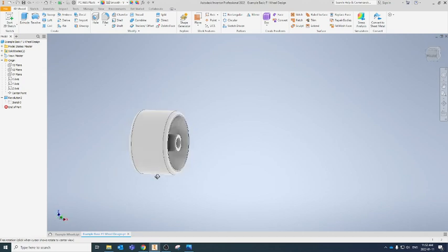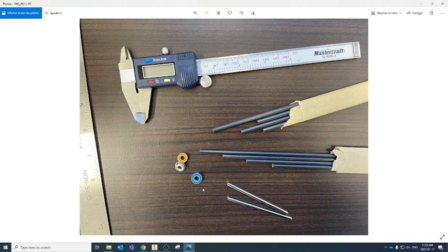Okay. Now, if you're using bearings, so if we look at this image again, we designed just for a plain axle there. If we're going to be using any sort of bearing, you have two options. You can either attach the bearing directly to the wheel, and then the axle will sit in the bearing which is in the wheel, or we could attach the bearing to the car body or the suspension system or the wheel support system which is on the car body, in which case you do not need to make allowances in your wheel for the bearing. So you're either designing it in the car body or in the wheel, basically.